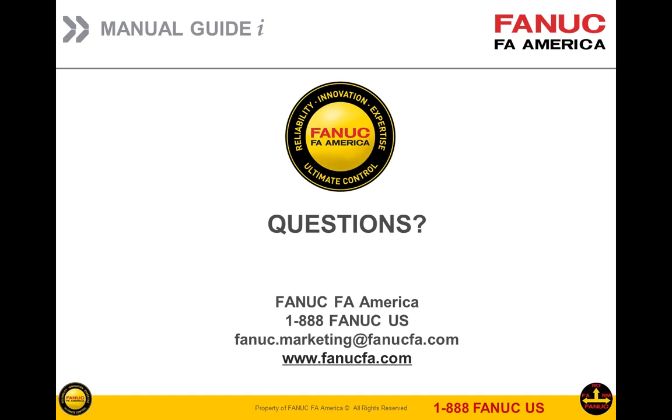Okay. Another question here. With castings, I work above the Z0 quite a bit. How does that work in milling cycles and drilling? Are all Z values absolute, or are some incremental? Well, when we do drilling cycles, it asks you for how you want to approach it. There's either initial 1, initial 2, or the R plane. So with the initial 1 and the initial 2, those are incremental values above the part. I think that answers it.